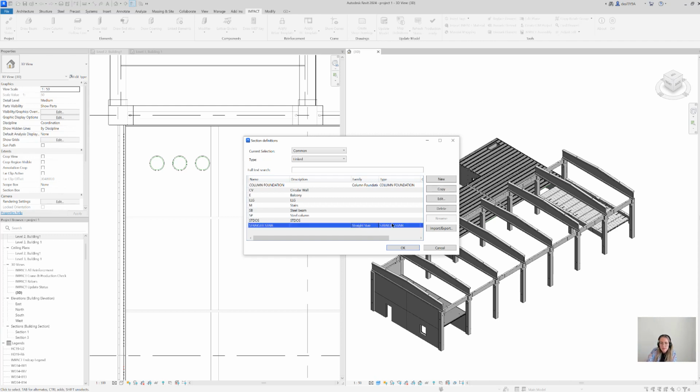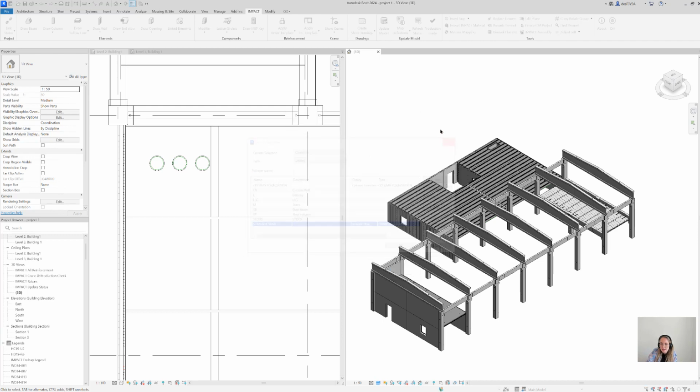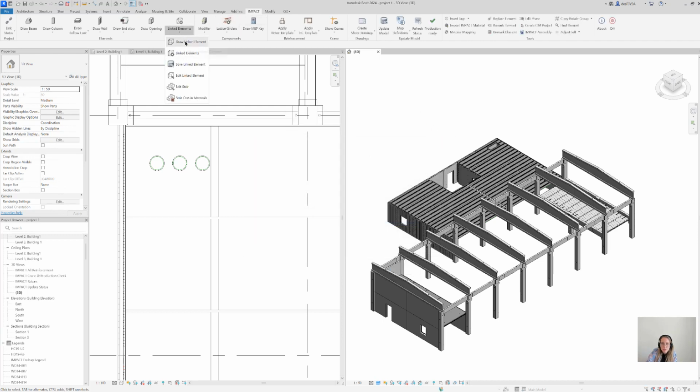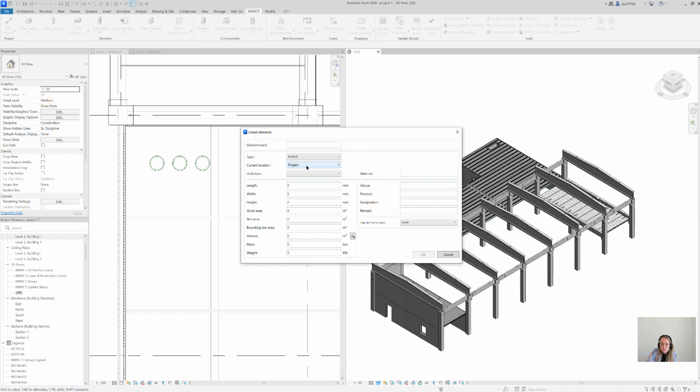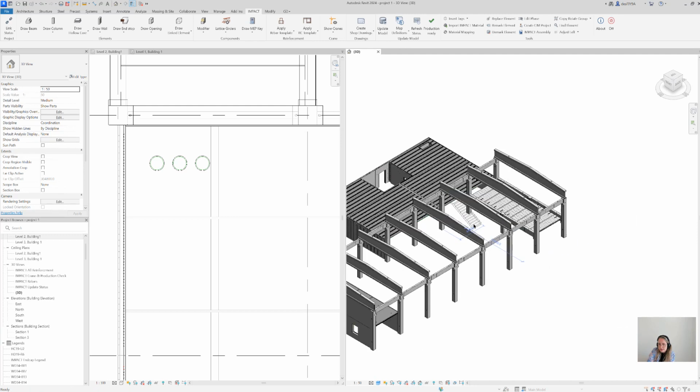And I want to draw this straight stair. It looks like this. And what I'm going to do is I'm going to say draw linked element. I think it was in common, yeah, and I used the straight stair. You can have predefined override parameters if you want in here. That's what we open for, and we're gonna insert the staircase.